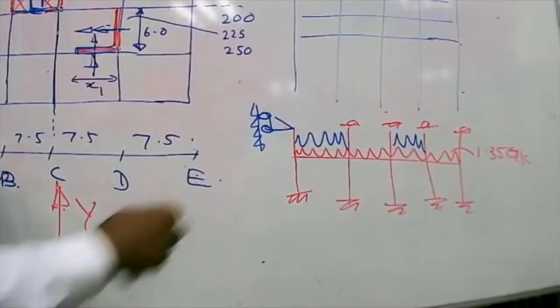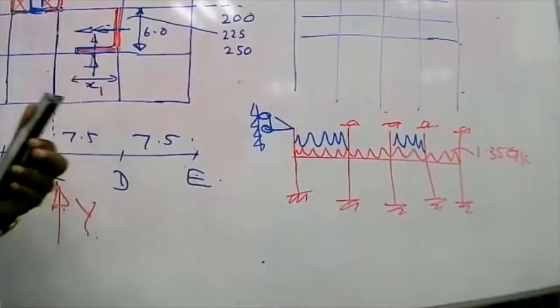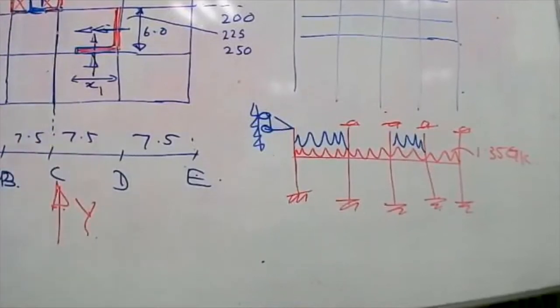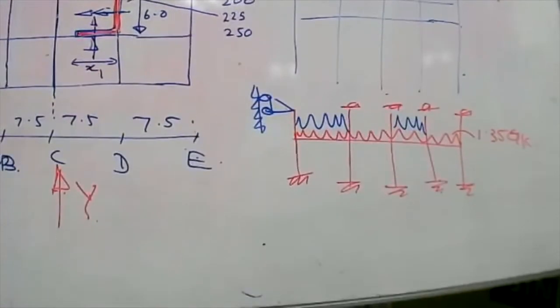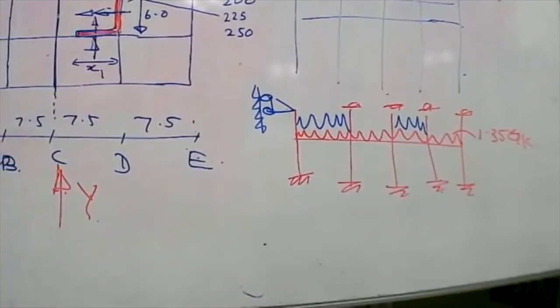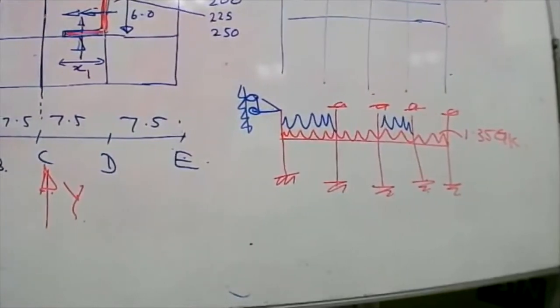What happens is the column will shorten, and if this point is fixed, the frame will start hanging from the top of the column, which is not going to happen. So you have to introduce a joint like this. You'll create pattern loading, use SAP 2000, create the bending moment envelope, and do the calculation.